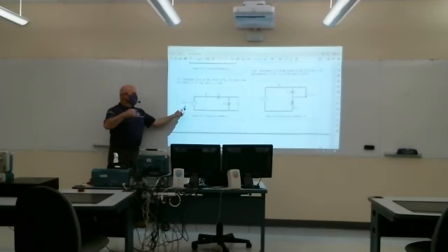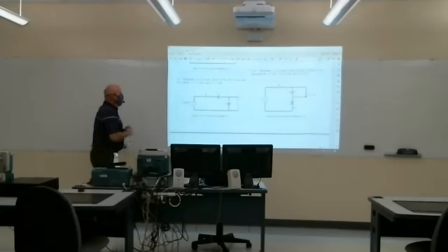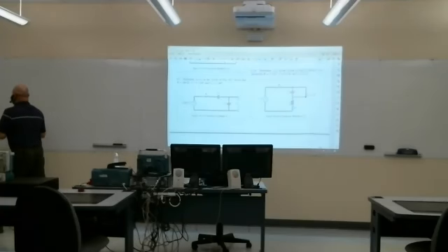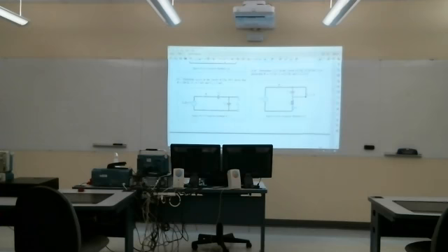But because there is no source that's active prior to t equals 0, there are no initial conditions. There are no charged capacitors. There are no inductors with current flowing through them. So we don't have to worry about initial conditions in this case. The first step, though, is to write the circuit in the S domain. So 200, and then